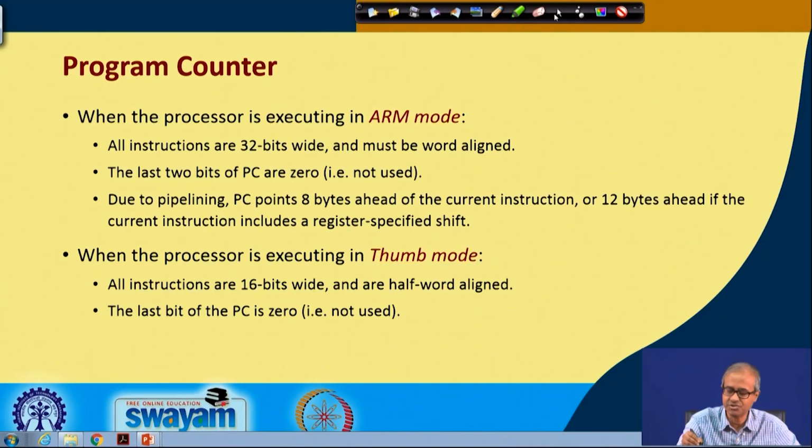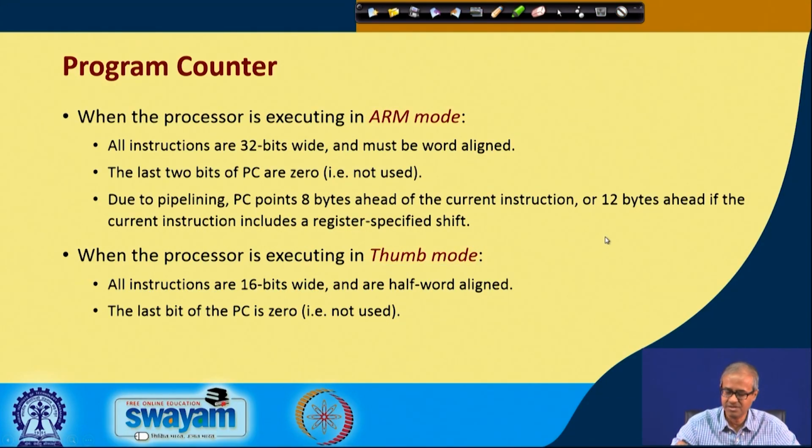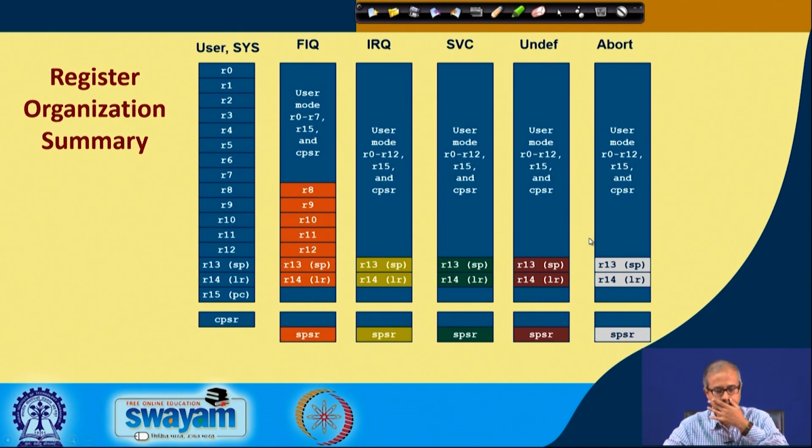because of which the total program memory required will be much smaller, and your code density will be much higher. For small applications, you can have a much cheaper implementation. So, Thumb mode is used for such cases where you need small systems.